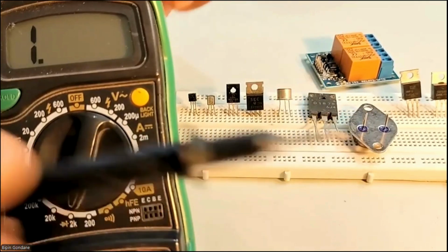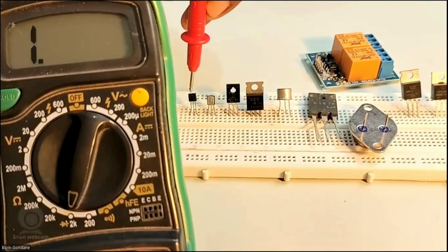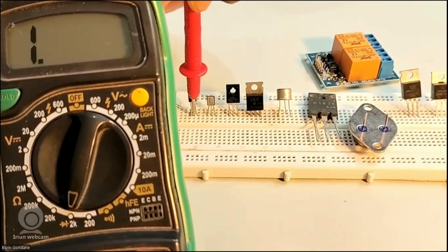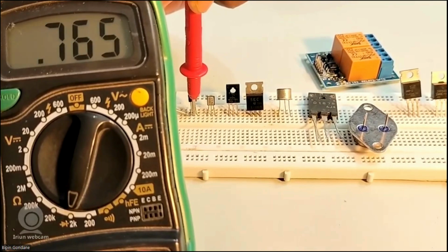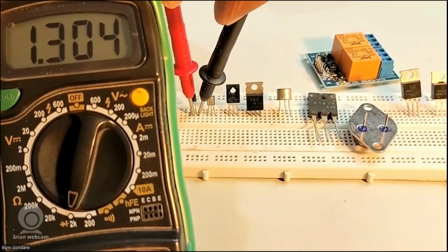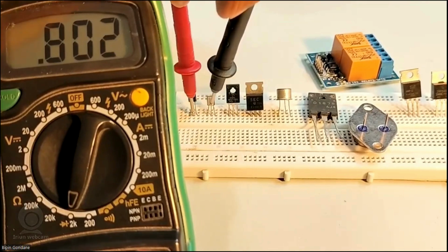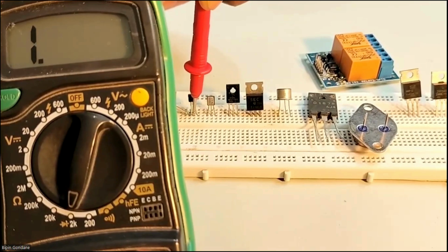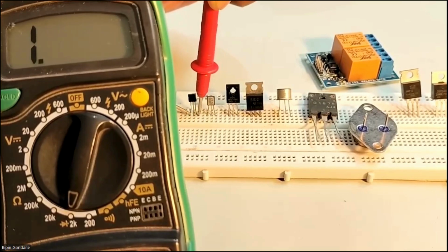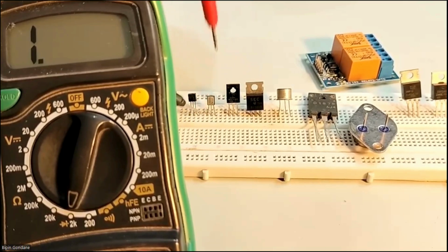So these two probes are there, black and red. I will just put one on the center point and test it. Okay, so you get a value. The other side also we will test. I'm putting it on the other side and I got some value. Approximately the value should be the same, with red in the center. And of course, we should also test the last one, that is emitter and collector. Suppose you don't know the emitter and collector, it's not showing, and reverse also you can check it.